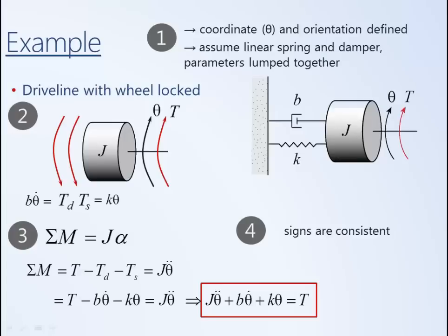You can sort of generate the torque speed characteristics that you want just by the way that you control the motor, by the way that you command voltages or apply voltages or current to the motor. So you don't necessarily need a clutch or a transmission.